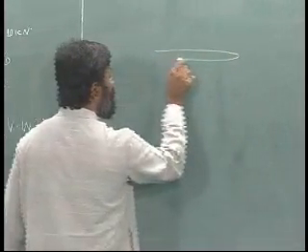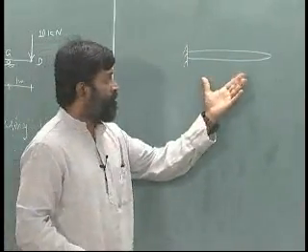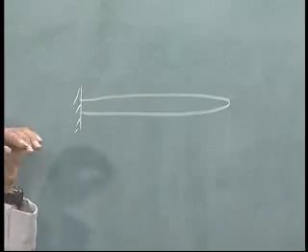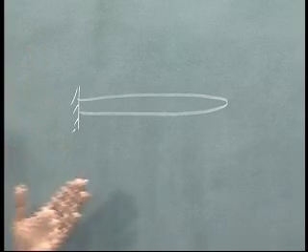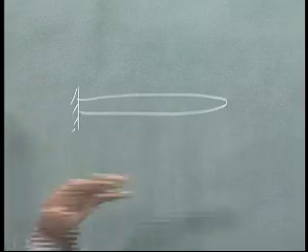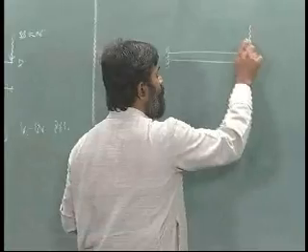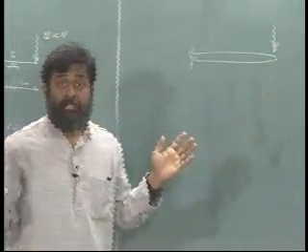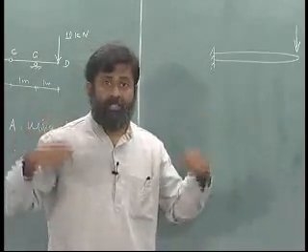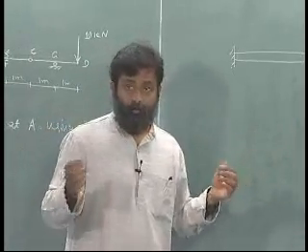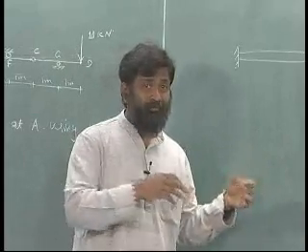If I have a beam like this, at this point it is prevented from rotation as well as movement. Okay. It is a beam problem, which means horizontal displacement is redundant. Okay. So if I apply a force here, is it going to be stable? That is the question I am asking. Okay. If it is stable, what is the degree of freedom I have? Is it positive 0, positive 1, 0 or negative?